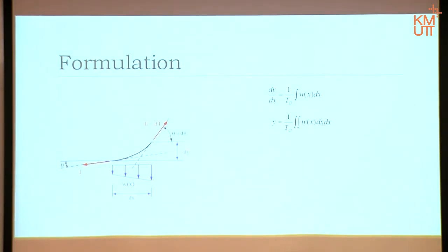Now, this is a general term, meaning as soon as you know the function of w, then you can substitute into that and start integrating. You have the relationship between x and y, meaning you know the whole shape of the curve. That is the idea. However, just to make it simpler for us to start studying it, we will assume that w is a constant, meaning it is distributed equally, the normal rectangular box we see.